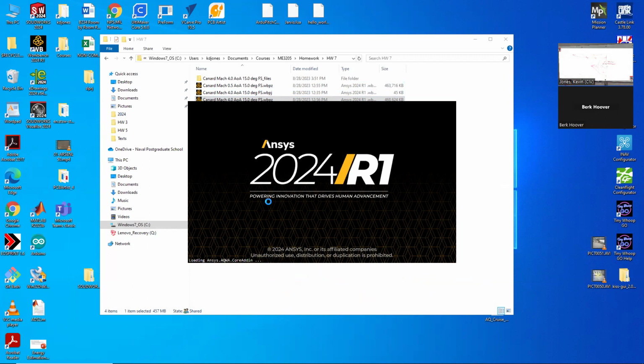On the supersonic one, up to 15 degrees, the convergence of RMS values looks, let's say, believable. We can take a look at it here. When you get much higher than that, if you look at lift and drag coefficients, they converge great. Fantastic. But the RMS values don't converge all that great. And I think we'll take a look at it here, but